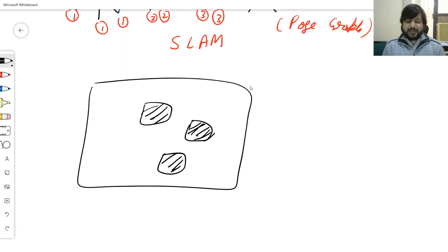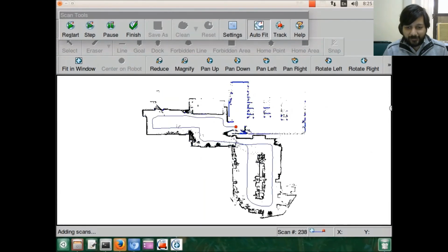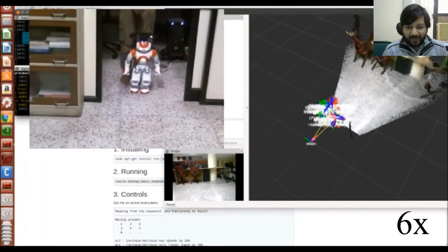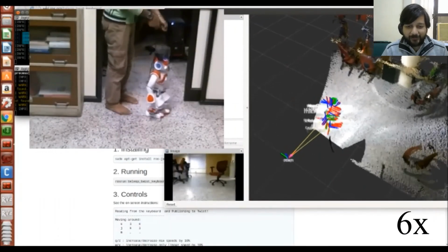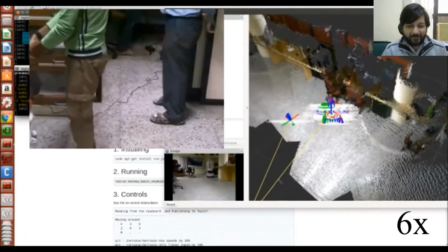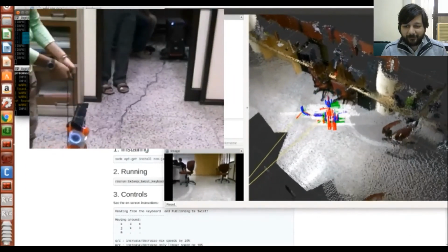And that constitutes the vision aspects of autonomous mobile robots. Okay, so these are practical examples of SLAM. The first one is by a LiDAR, where you see this robot going and just projecting everything on the canvas and calculating its position based on how the different corners have moved. That's again the one that you see. The next is the Microsoft Kinect, which has a depth camera and an RGB camera, wherein the robot is looking at different corners and projecting them up.